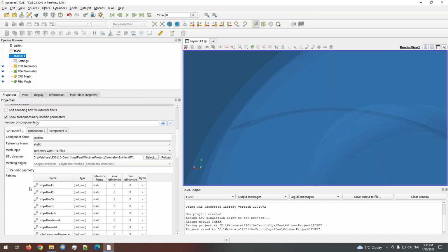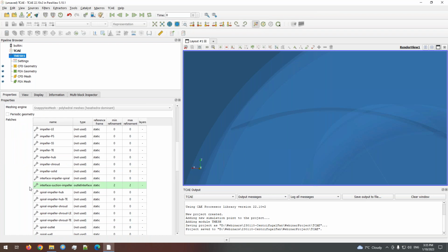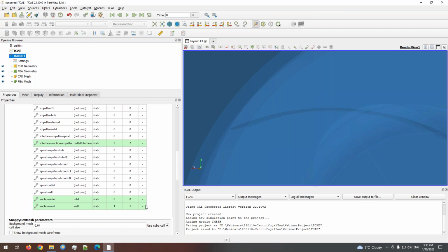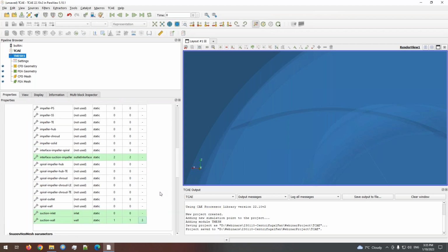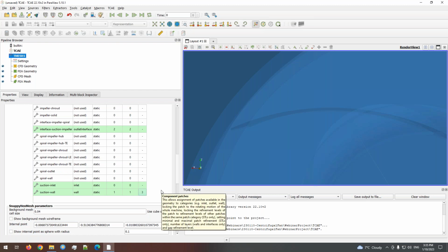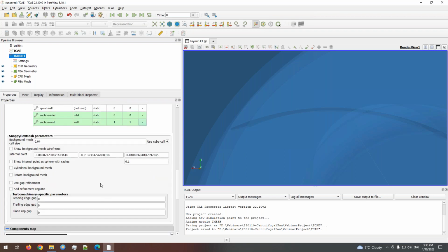Okay, maybe I don't want to add the boundary layers for simplicity and to have the simulation quicker, but you can set as many boundary layers as you want, depending on what you need to achieve. Let's say snappy is robust up to 8 or 9 boundary layers. Usually we use up to 5 for industry applications. But in this case, I don't want to add the boundary layer.